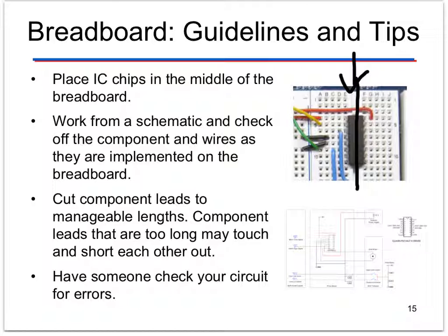And the leads on wires need to be cut to manageable lengths. If your lead is too long, then your wire can touch other things and then they short out. And always have someone check your circuit for errors.